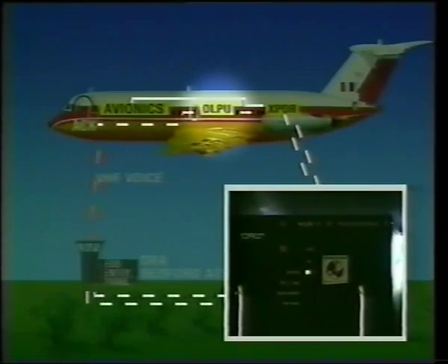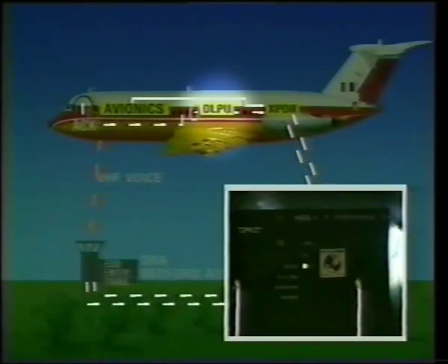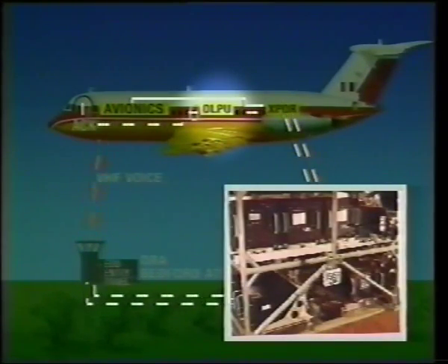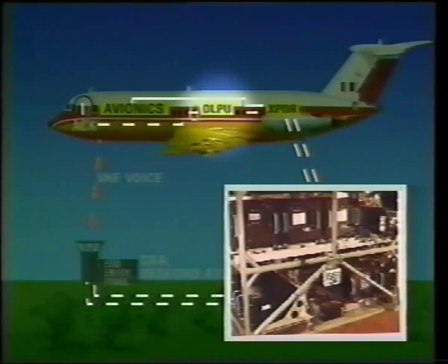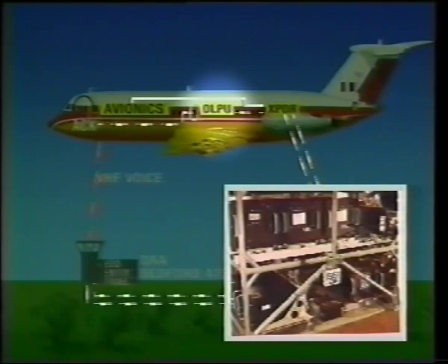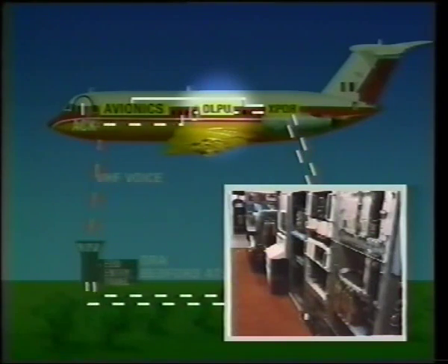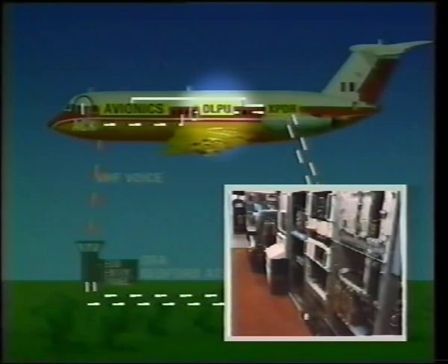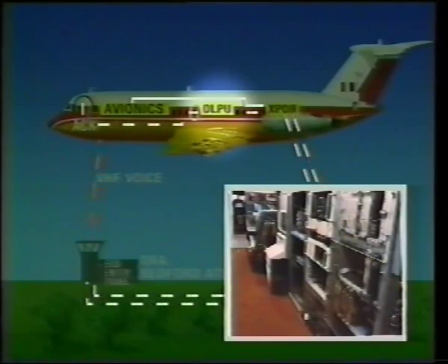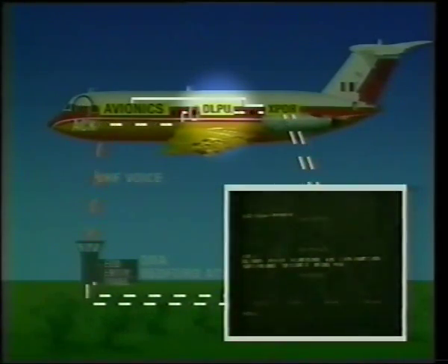The data link processing unit enables automatic extraction of information from the aircraft systems, as in Scenario 1, in addition to the handling of ATC instructions and acknowledgements and VOLMET interrogations in Scenario 2. The pilot DLPU interface in Scenario 2 is handled by the onboard general-purpose computer.